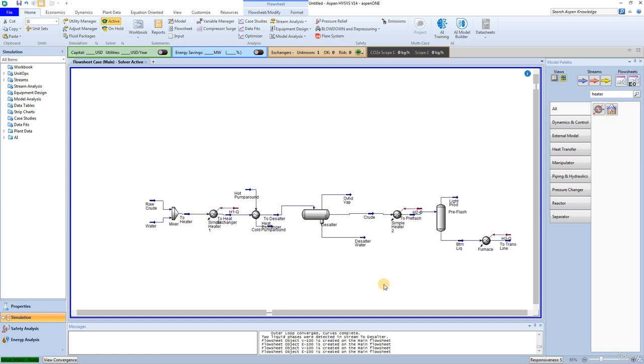The pipe segment is a very versatile piping operation that allows for single and multi-phase flow, customizable piping geometry, and various heat transfer considerations. Flow assurance capabilities such as slug flow and erosional velocity calculations further enhance the capabilities of the pipe segment. You can build the pipe segment to whatever level of detail you wish depending on the simplicity or complexity of the piping configuration you are studying.